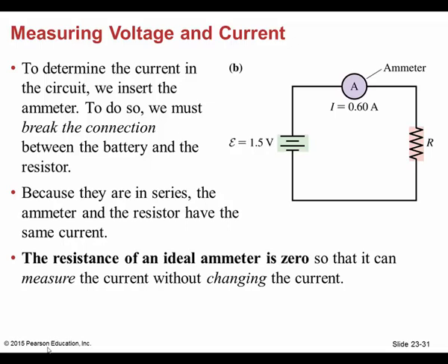Now, notice here that when you check the current in a circuit, you have the positive going in and the negative coming out. What do you mean? In other words, you put your ammeter in series. Notice you've got a single pathway for current to flow through that ammeter. That's why you always have to hook up your ammeter in series in a circuit.